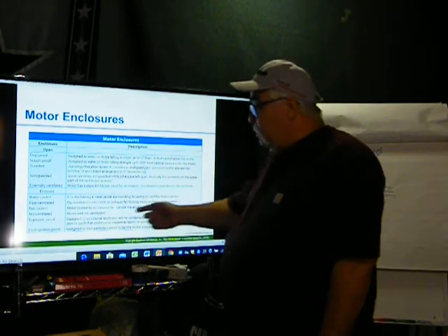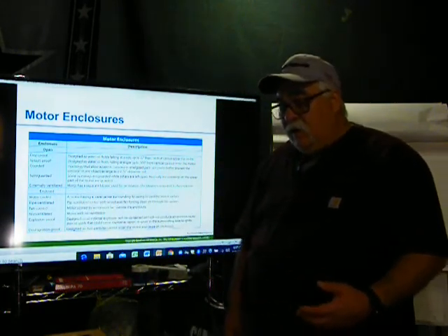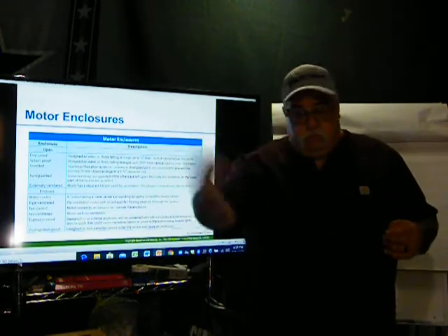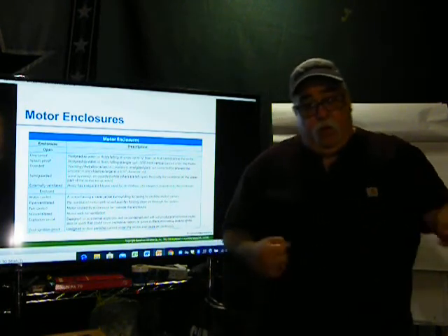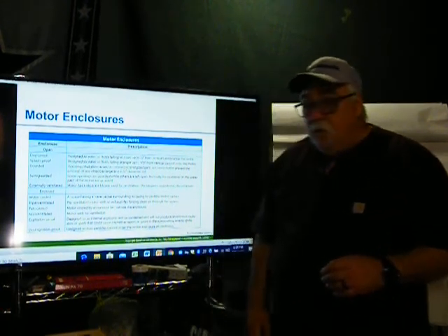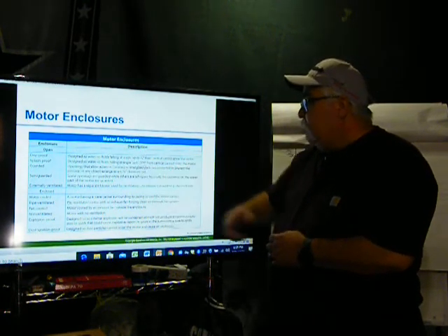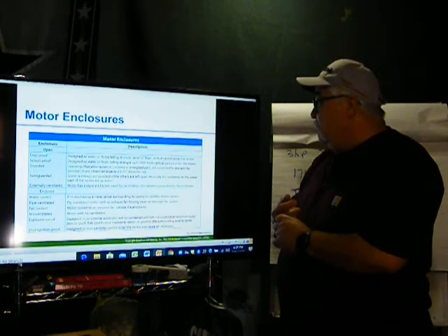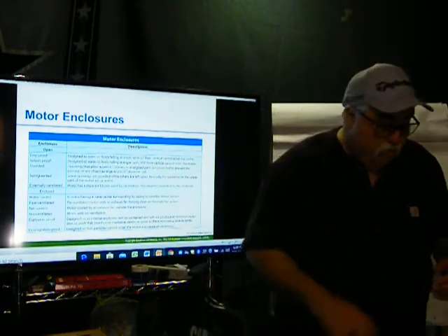The only reason I kept telling them that we wanted an enclosed, an encapsulated motor was when they go in there and they were washing these things down, they just got water. You can't tell which direction it's going to be pointed where the motor was at. So we wanted to make sure it wouldn't get in. That would fall under that splash-proof design, so water and fluids falling at an angle up to 100 degrees from vertical cannot enter the motor. Again, we didn't want water getting in because we didn't know which way it was going to go in.